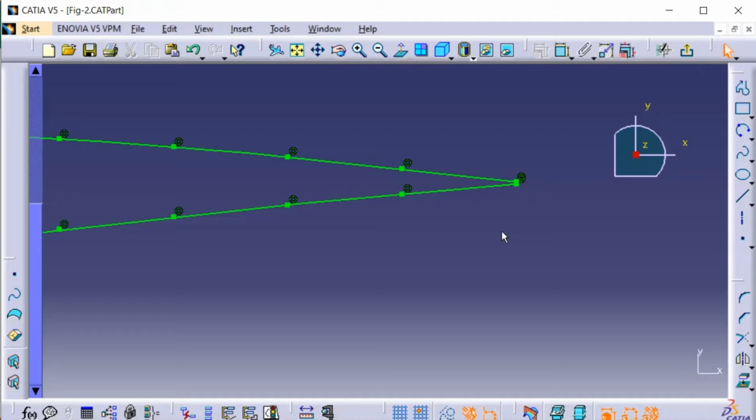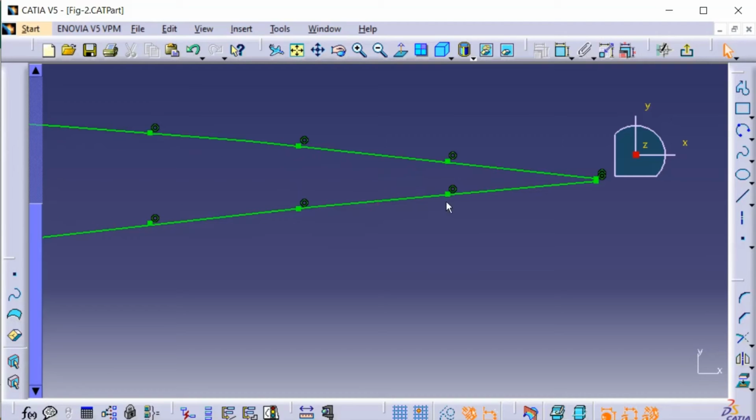We need to trim the extra portions of the spline or profile so that a completely closed aerofoil loop can be obtained. So we have to decide which parameter we have to control while modeling so that the procedure can be adapted accordingly. If we want to control the leading and trailing edge radius, then we can do something like this.